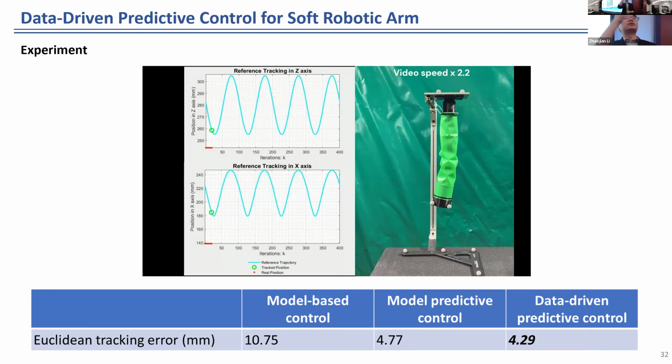Scientifically, those are very interesting questions. With visual servoing or active perception, you go around the fruit at different angles, and then you can do better 3D modeling and orientation estimation. Those are possible, and we also explored them in the past. But practically, this is very hard to implement, because for one fruit you have to go to different directions, which will significantly slow down the process. So scientifically interesting, but practically, this will be hard to incorporate.